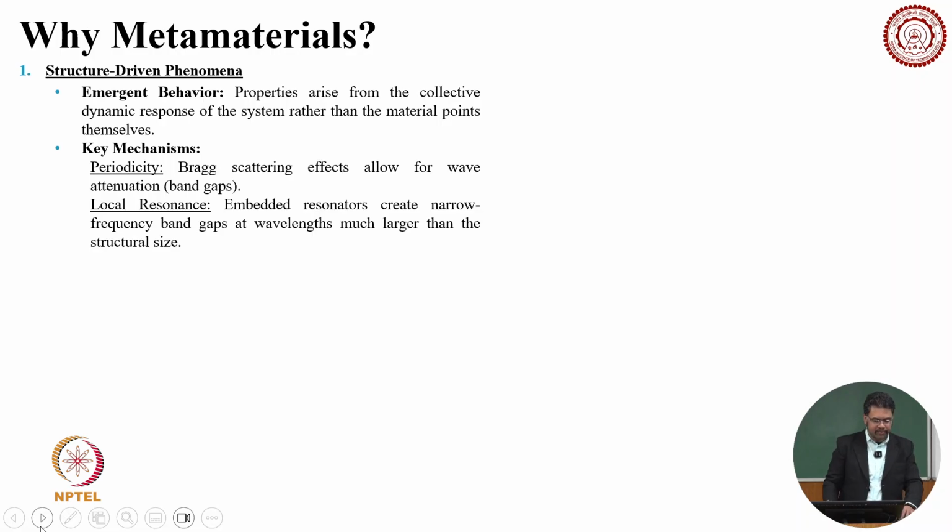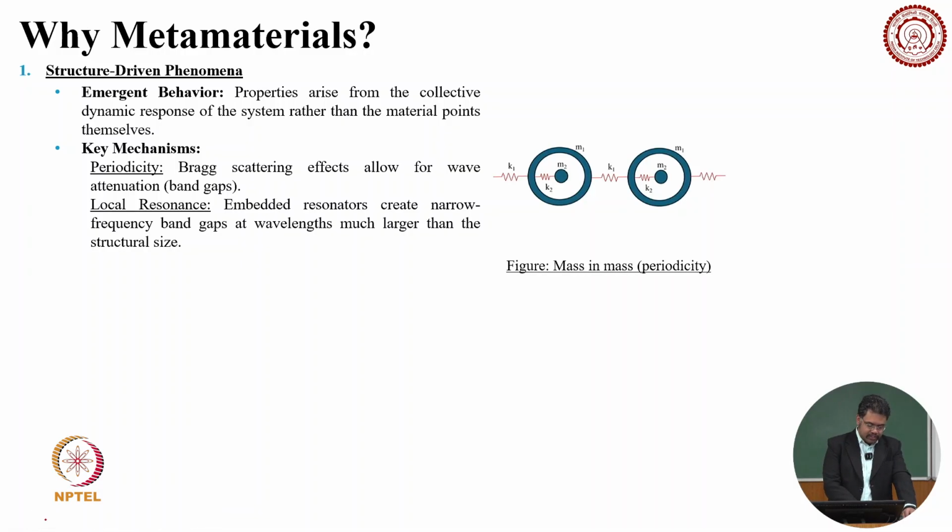Now why metamaterial? Structure driven phenomena, like a sum of the emergent phenomena, like properties arising from the collective dynamic responses of the system rather than the material points themselves. Key mechanisms like periodicity and backscattering effect allow for wave attenuation and band gap. Local resonances, that is embedded resonators, create a narrow frequency band gap at wavelengths much larger than the structural size.